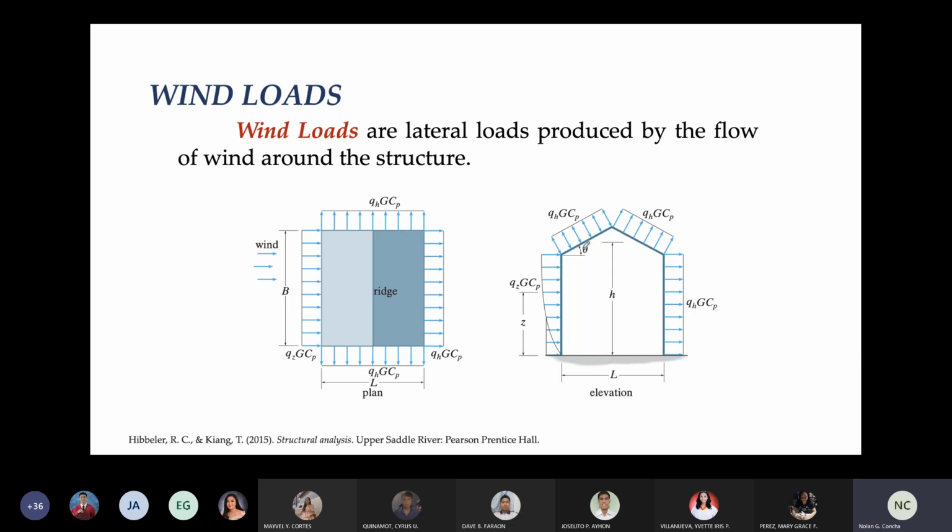Para yung steel frame, yung steel truss, hindi mag-carry ng excessive wind load. Kasi magpa-pass through lang naman yung wind doon sa structural frame nung billboard. Kaya walang masyadong wind. Kasi hindi mo naman hinaharangan yung direction niya. So magkakaroon ka lang ng significant wind load if you are blocking the wind direction.